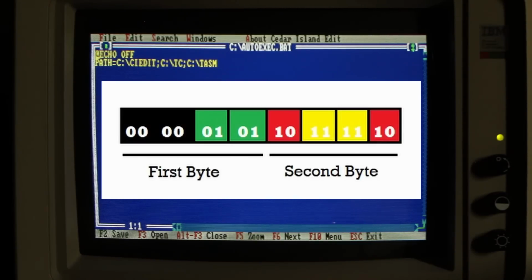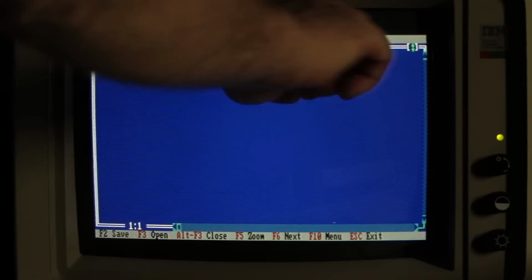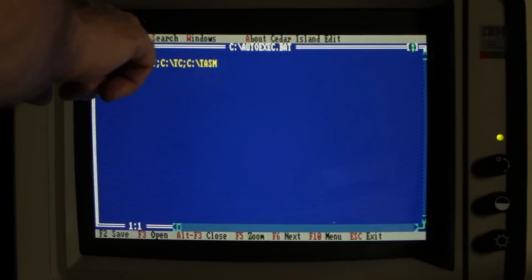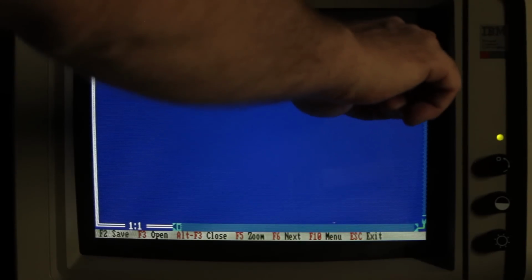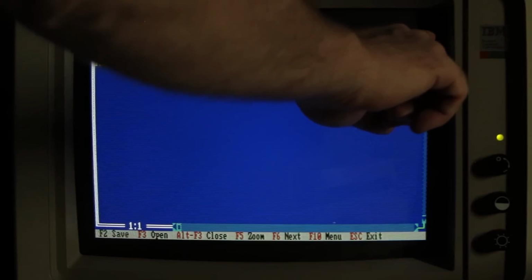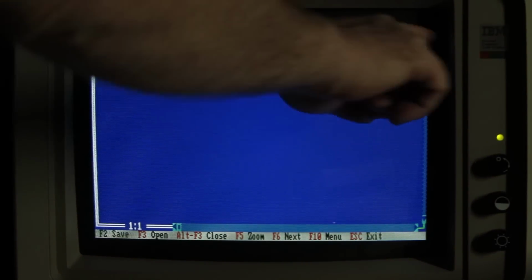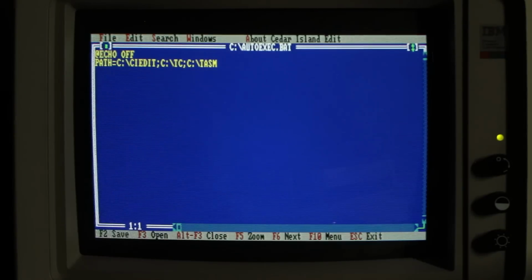And the other complication, of course, is that there are multiple scan lines per character row, and the CRT controller chip doesn't know any different. So one way of fixing that would just be to tell it, I only want 1 scan line per character row, and that would mean that it'd get to the end of just 1 scan line, decide that it's done with that entire character row, and then go on to the next character row and so on.